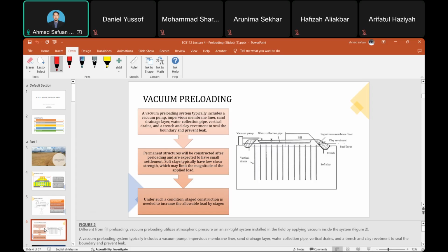First we need to know the desired height to build for any geotechnical structure, for example, an embankment. However, we cannot construct the preloading at one time. So what should we do? We need to construct it in stage construction.